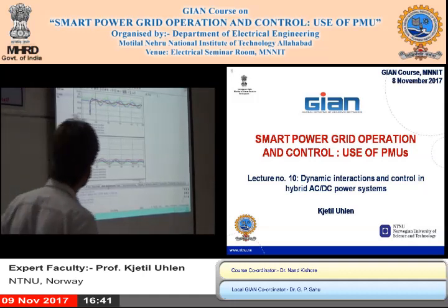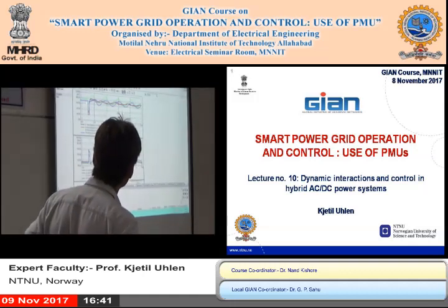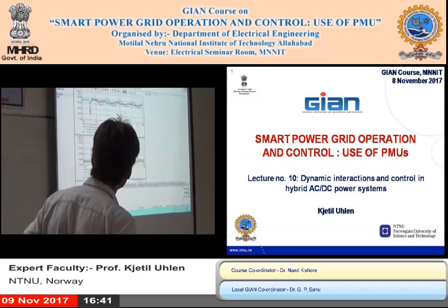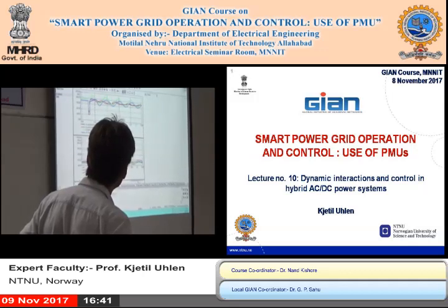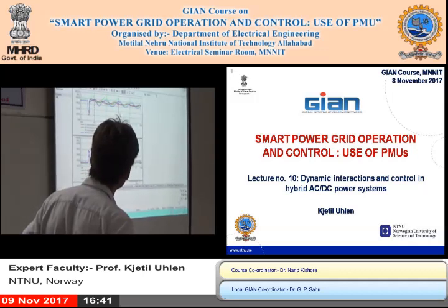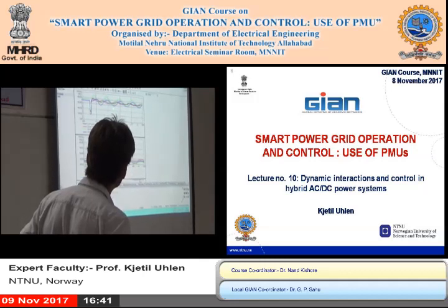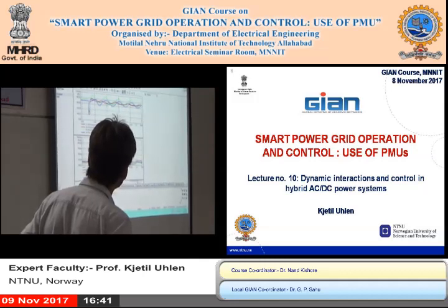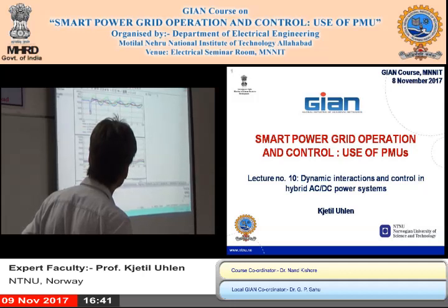That's up to you. But here you see the short circuit and that there are power oscillations. Generators 3 and 4 are obviously in phase. But generators 1 and 2 are somehow out of phase, and it's not clear what their frequency is either.